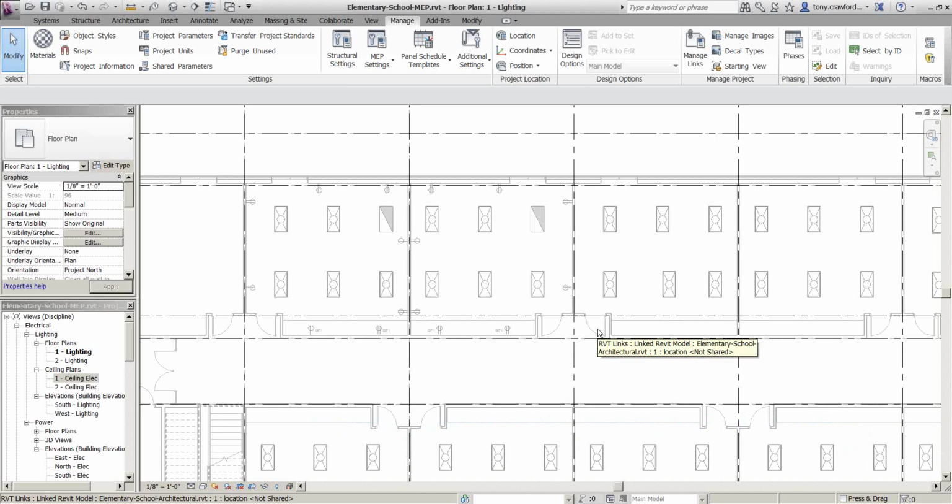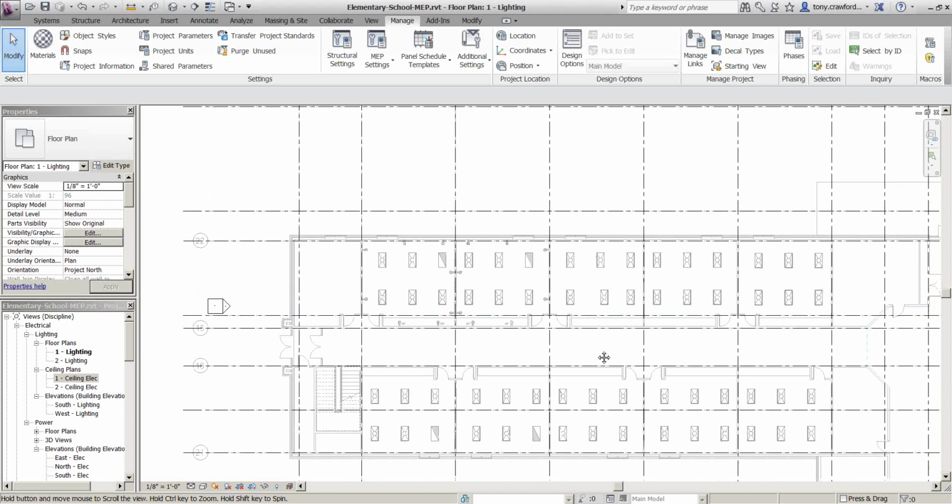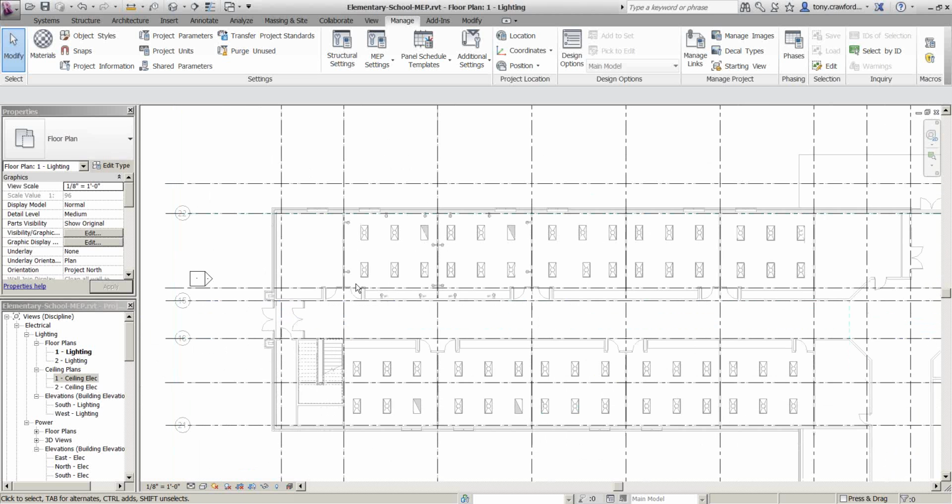Because they didn't line up, that's the reason that some firms choose not to use this tool, because then you have to go in and move them manually. And you can, depending on how they came in. I may be able to manually adjust; if there's 50 lights in here, I could move 50 at the same time, because they'll probably come in consistent anyway. They'll all be off by 2 feet, 2 feet to the south.